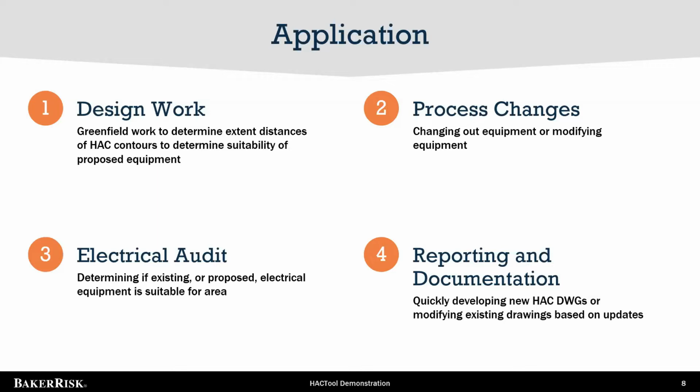And that kind of ties into number 3 there, the electrical audit. So determining if existing or proposed electrical equipment is suitable for the area that it's in. And so HACTool has the ability to quickly generate tables for electrical equipment that may be out of compliance or may be damaged in a classified area, which we'll see in the software demonstration. And then number 4, we've alluded to reporting and documentation, really developing these customizable HAC drawings that you can zoom in and get the specific view of what you're looking for in a classified area, a real neat and useful feature coming out of the software.